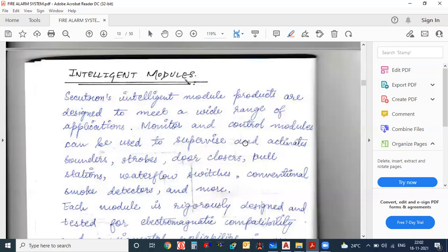Also, for ventilation inside the car parking, we have make-up pressure fans. This is for the fresh air, and there is a fire smoke ventilation fan. In case of fire, it will be activated, or if the CO, carbon monoxide, ppm is very high, it also will be activated through the fire alarm.